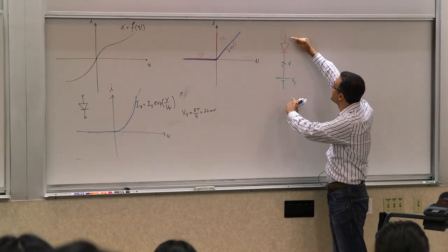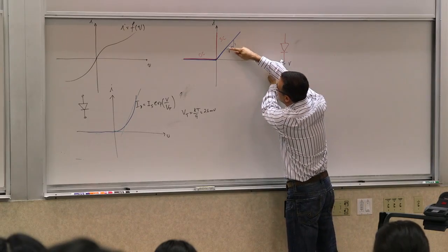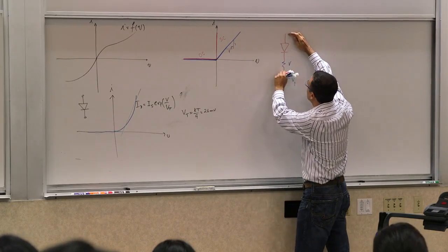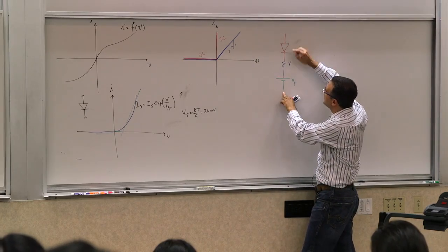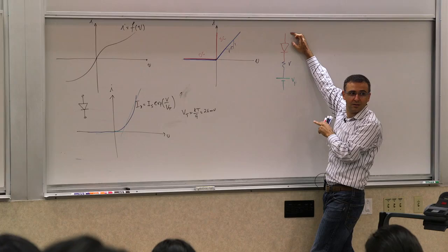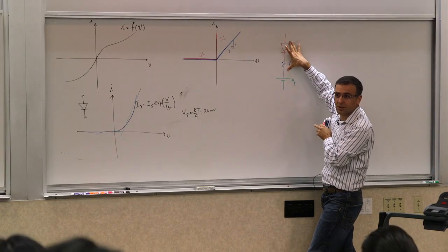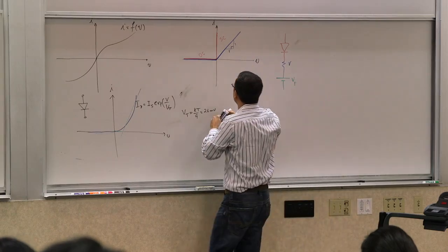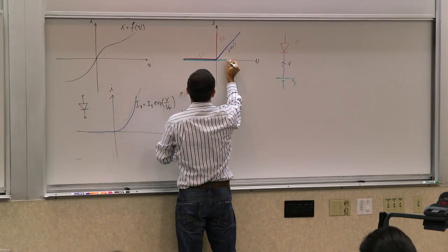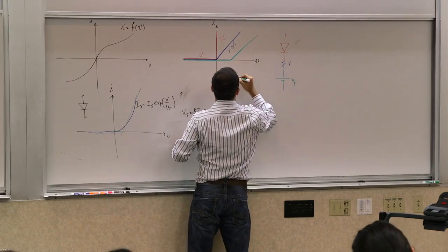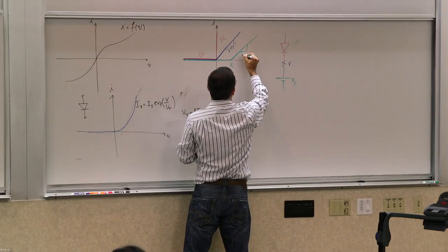I'm going to say it again. So assume that the voltage source was not here. To produce a certain point in this curve, you need to apply a certain voltage, right? Now that this voltage is also in series, you need to apply this much more to get to that point across these two, right? So it shifts this to the right. Once I add that other voltage source element, the curve becomes like that, and this becomes that V1. And that's still the same slope.